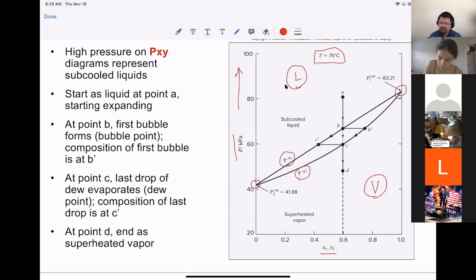We are going to have the analysis where you move from the liquid phase, and you try to have the first bubble over here, right? So that is PB, still the bubble pressure. Or on the other side, if you are moving from the composition D all the way up to the mixture region, then PC would be the dew pressure. This is the dew pressure, this is the bubble pressure calculation, right?